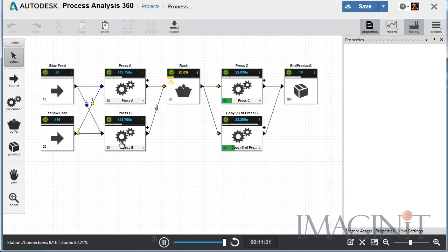At any given time, you can come over and simulate a failure in one of your devices. So in this case, I want to simulate what one of the first presses falling out of the process would do to the overall simulation. And you can see that even with this press falling out, we generated 20 objects in about 21 minutes, about half the time of the original design.